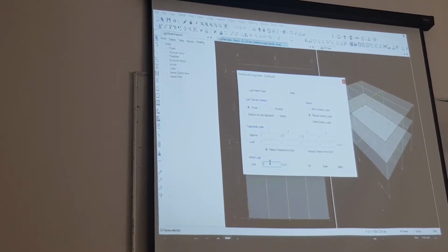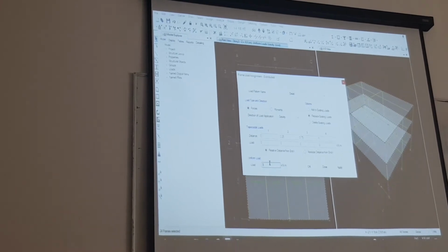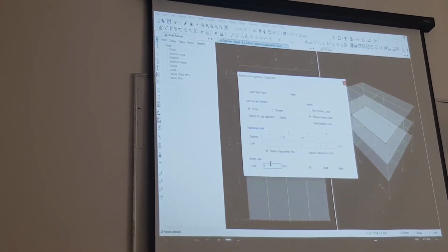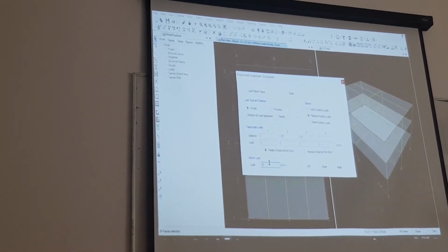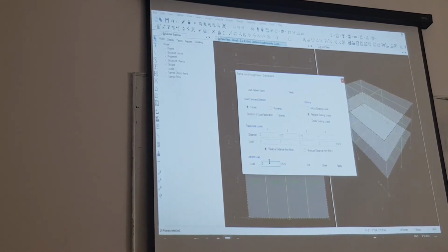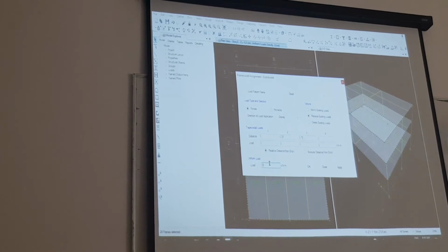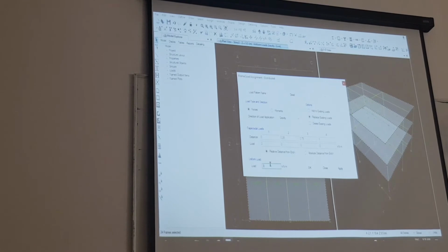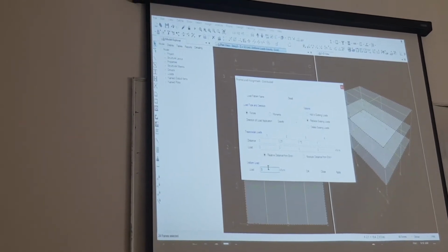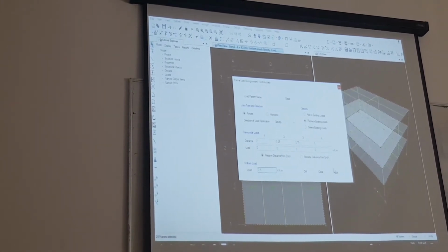You have to take the perimeter of that particular area and then apply this. First of all, you have to see what the length of the beam is, then what the unit weight of the block you are using is, how many blocks you need for this particular length, and what the total height is, and calculate it accordingly and convert it into kilonewtons per meter. Okay, you know all this stuff. It's basic. Oh yeah, sure. So let us apply 2.5 and click apply.